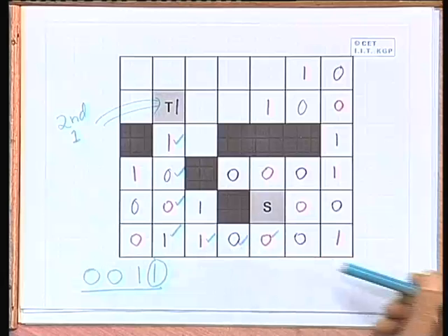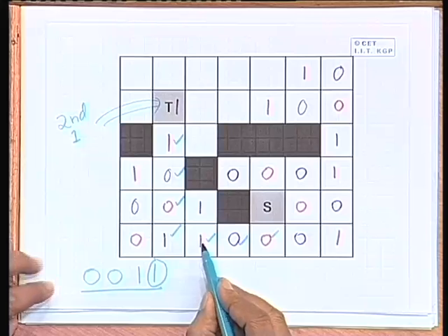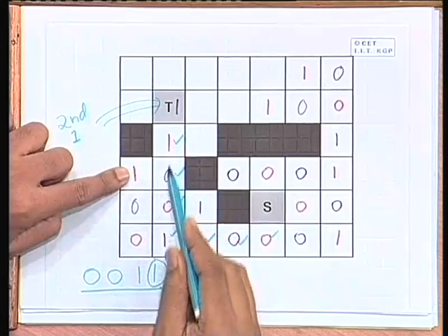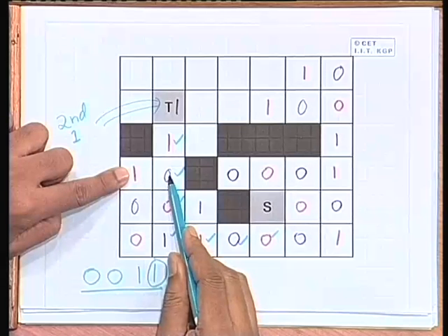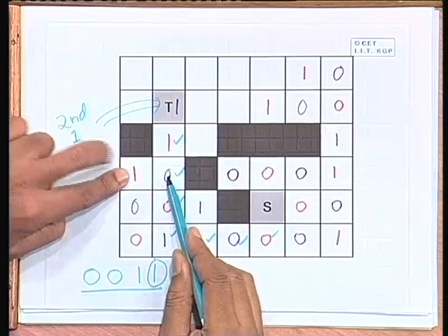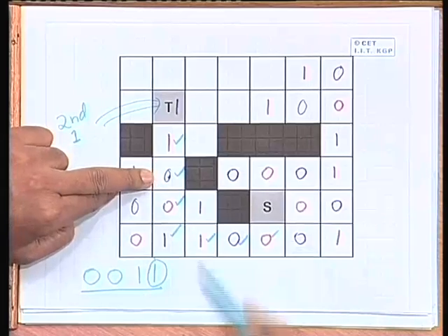So, this is an improvement of Lee's algorithm you can have with very little overhead. But previous one? Just this one, the example you said. This example one, okay. Yes. If you go from third from the bottom and the first column, third from the bottom and the second column, this 0, this 0, yes. This 0 you can reach from a 0 and you can reach from a 1. Yes. Okay. But again there is the same ambiguity, like you are doing 2 paths and now you are not sure which first one you are labeling.